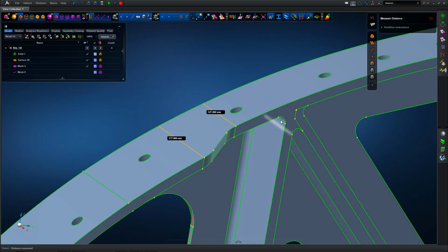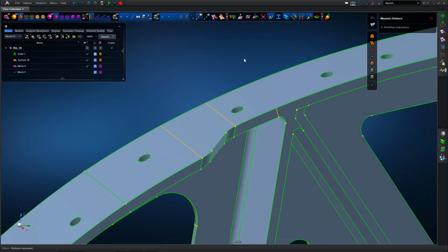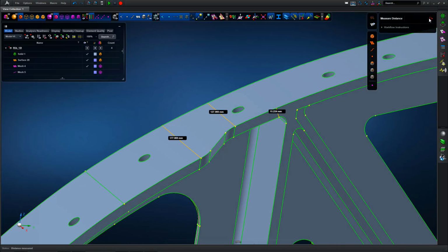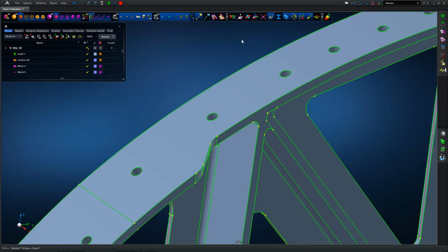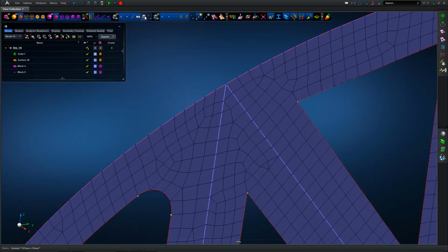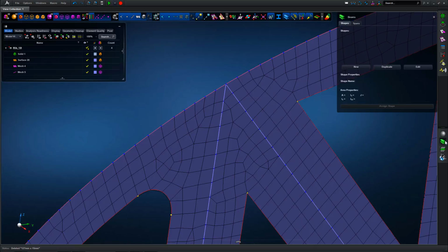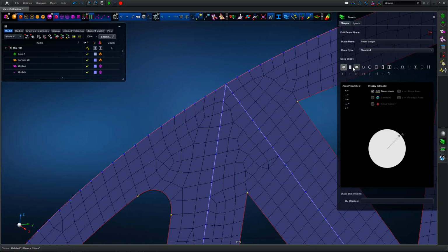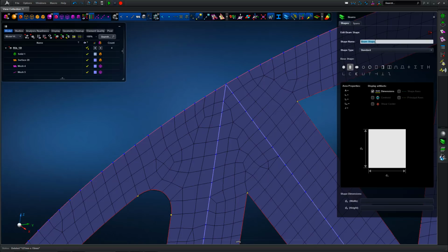So making some measurements across the width of the flanges. We've got 127 and 177 for a different dimension, and then 15mm thick. With that in mind, we can go into the beam attribution tool, and we're going to define our sections first of all. So pick rectangular section, put the shape name in, as Apex calls it.